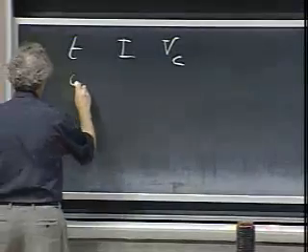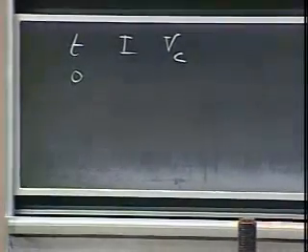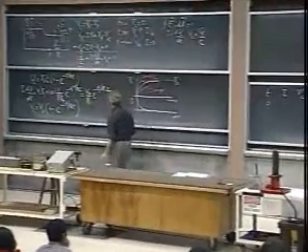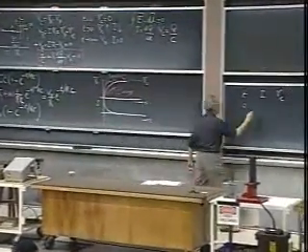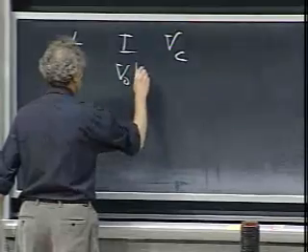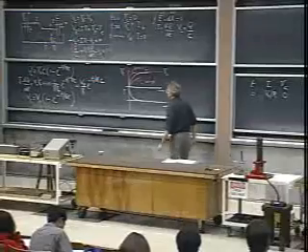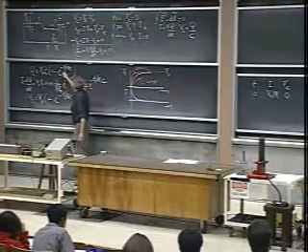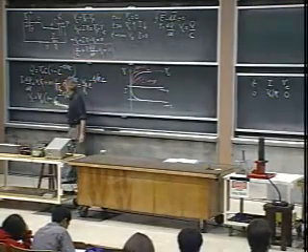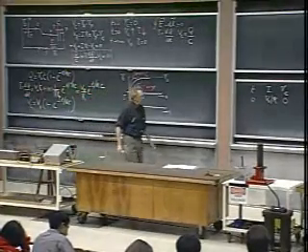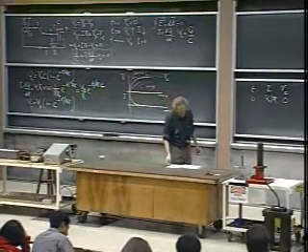And when t is 0, you go to your equation of I. So this is 1. So you have a current V0 divided by R. And V of C is 0. You can see that. If t is 0, you get 1 minus 1, so you see indeed that the potential over the capacitance is still 0.